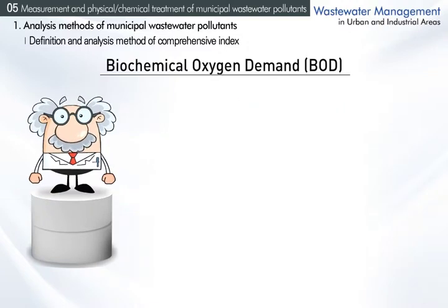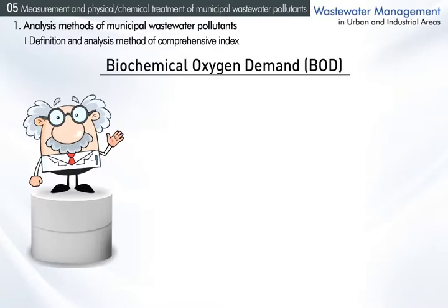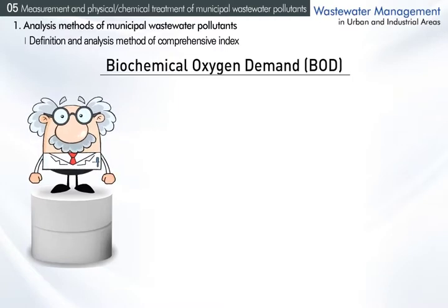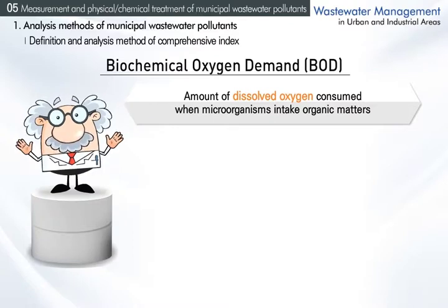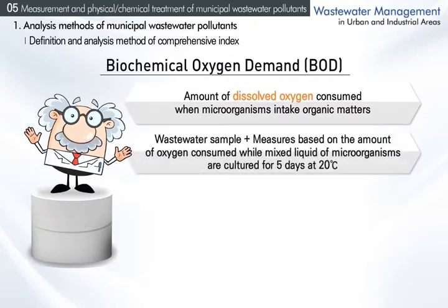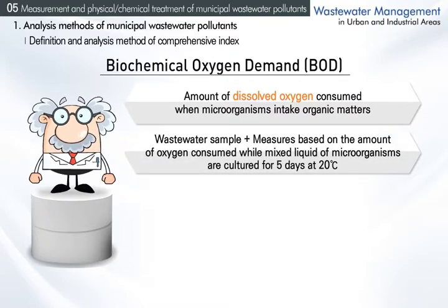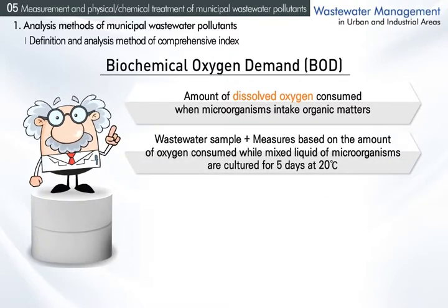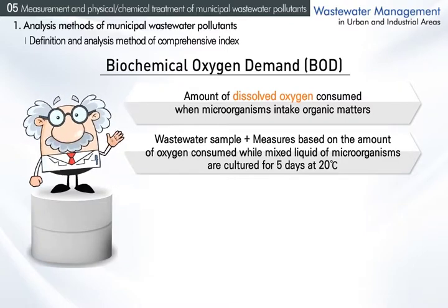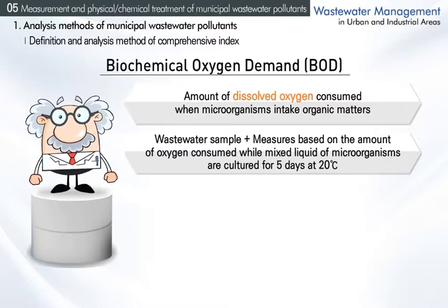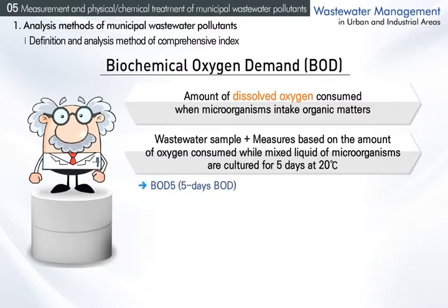To summarize, BOD is the same as the entire amount of dissolved oxygen consumed while microorganisms intake organic matters to produce energy and synthesize new microorganisms. In addition, the amount of oxygen consumed while the mixed liquid of wastewater sample and microorganisms is cultured for 5 days at 20 degrees Celsius is measured as standard and is shown as BOD5 to clarify this fact.